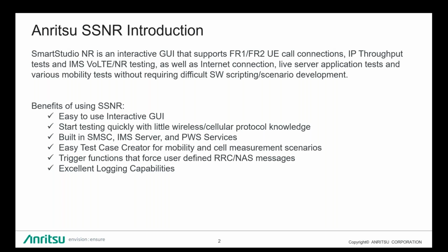Another thing that we support here is SMS, MMS verification testing with the SMSC, CMAS, ETWS, emergency alert verification with the PWS server that's installed, and also VoLTE and voice over NR with built-in IMS servers. There are also a variety of ways that we could do trigger functions for sending failure type scenarios via RRC and NAS messages. In addition, there's excellent logging capabilities on this particular setup.